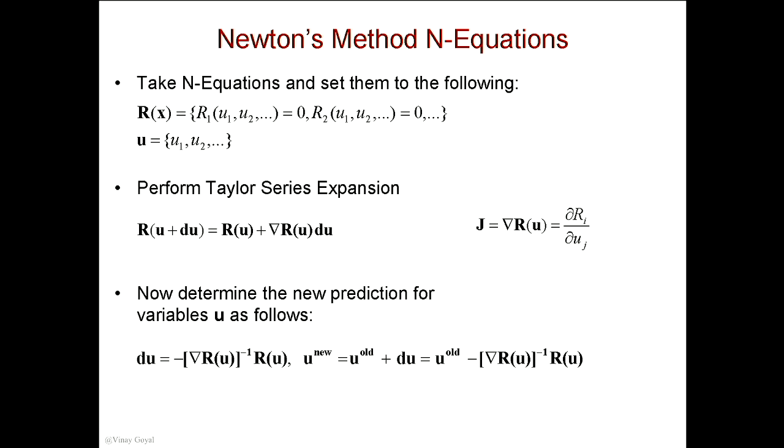You have to calculate this matrix, which is fairly large. It will be 1,000,000 by 1,000,000, okay, in this example. And so, do you agree that I want the residual to be 0? Right? So then I have to solve for this delta U. And so I have to take this to the other side of the equation and invert it. And so that's why I have this equation to correct the deflection. So U new is U old plus a correction dU, which is based on that formula. And so that's what I get there. Okay? So that's the correction.